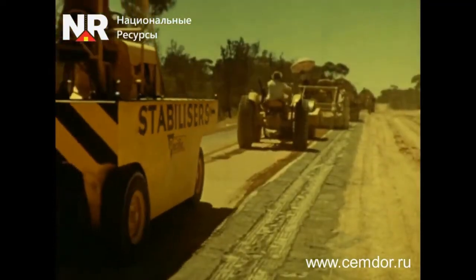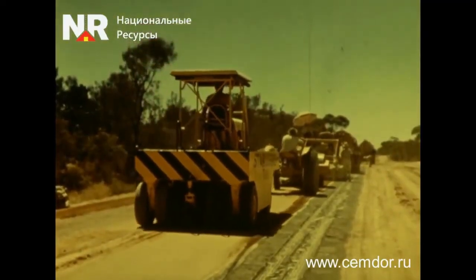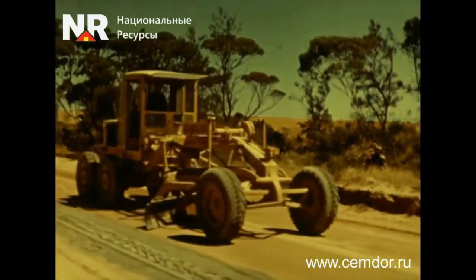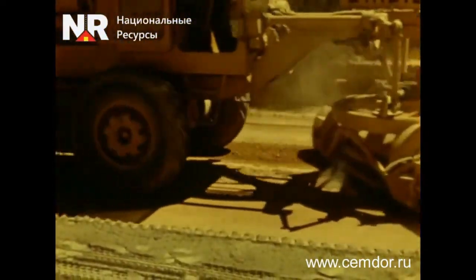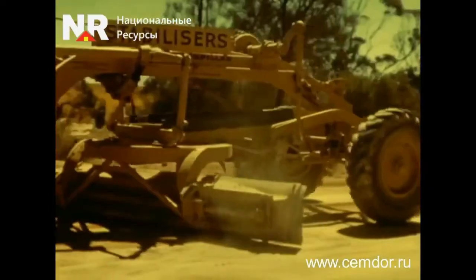Pneumatic rollers are usually used for final compaction. During compaction, the surface of the structural layer is graded with a grader to avoid irregularities that could later cause various types of defects. At the same time, the road surface is also cleared of any foreign objects.